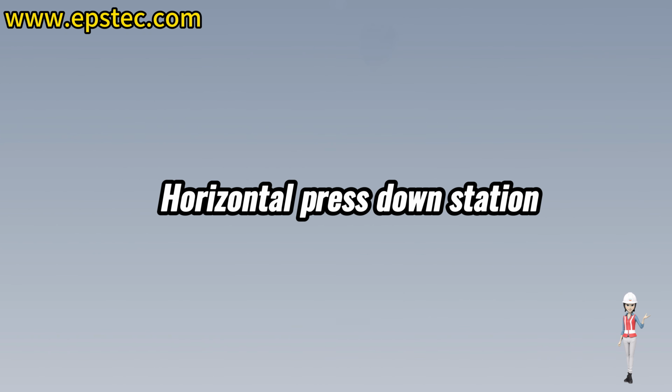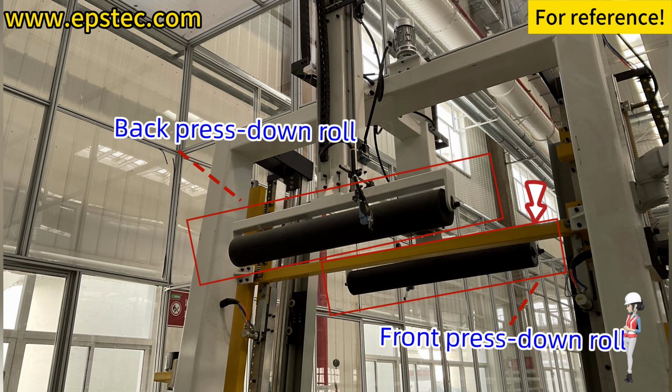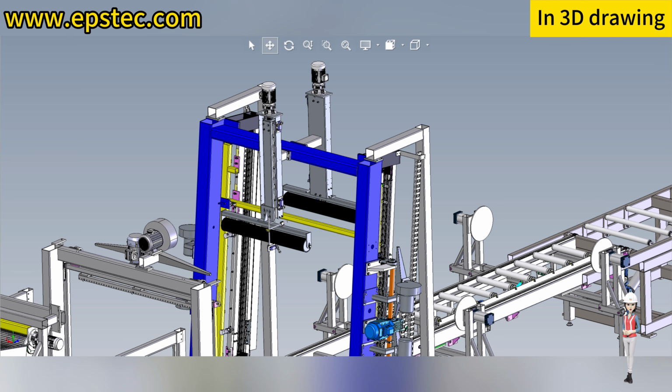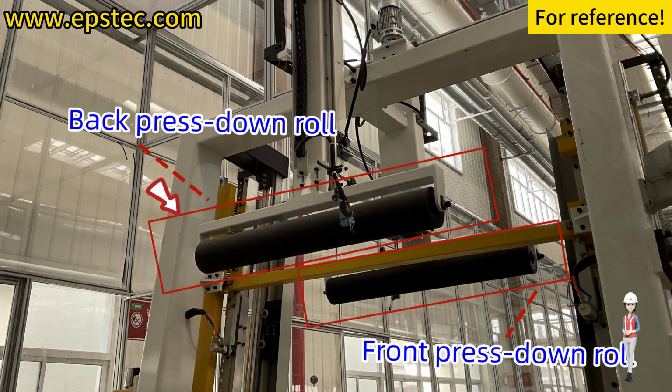Horizontal press-down station. When the head of the EPS block reaches the position of the second photoelectric sensor, the front press-down roller moves downwards until the roller contacts the surface of the EPS block. When the tail of the EPS block leaves the position of the first photoelectric sensor, the back press-down roller moves downwards.